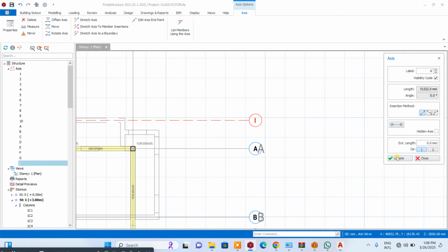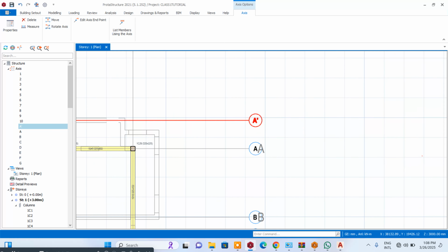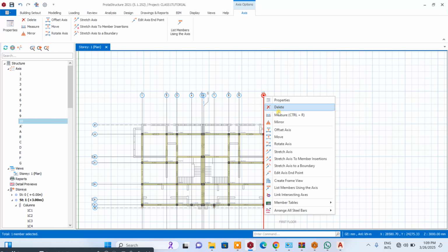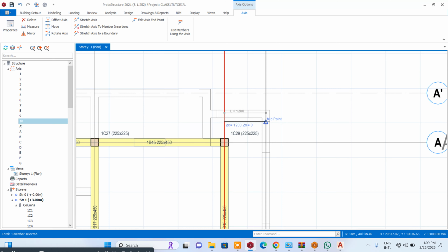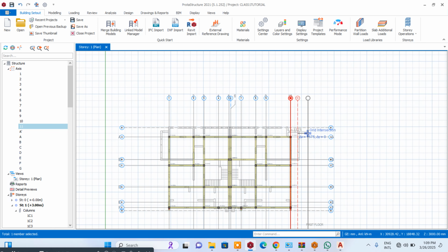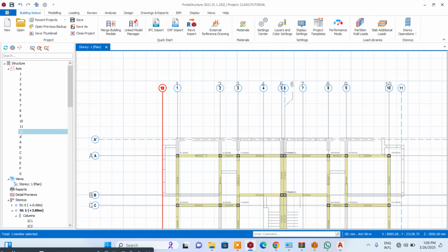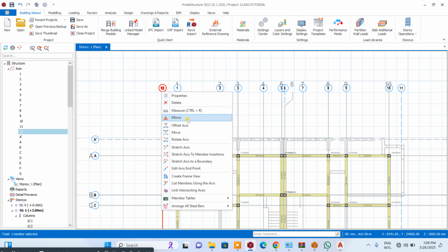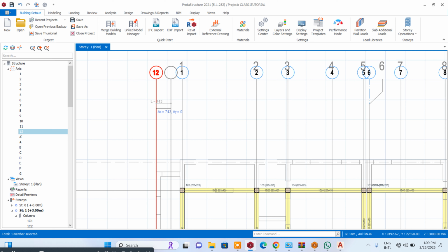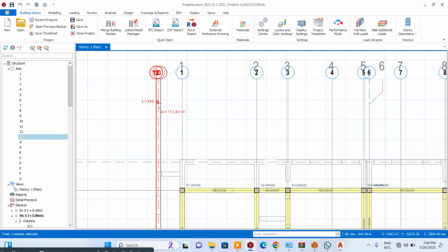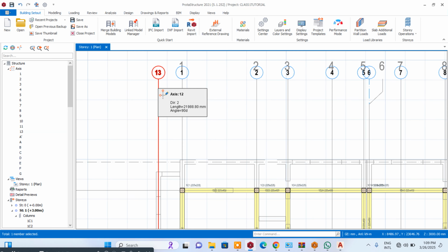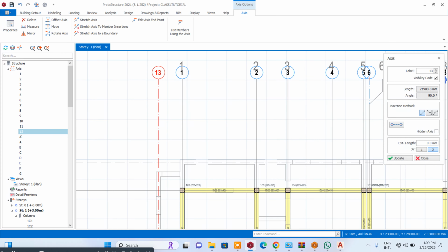A prime. So offset this too. Okay, let's offset here too. Offset. Control F2. 112.5. Give it the center. You have your grid at the center. Then you delete the first one. The first one was actually a guide.